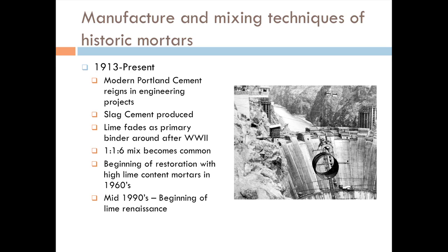And when you say lime, and you're talking about Portland mix, then you're also talking about something that was kilned at a higher temperature than the 900 or so that you were talking about, or are you talking about the regular hydraulic lime? I'm talking about just regular hydrated lime. When I'm referring to lime, only hydrated lime. That's what we buy today, and that's what's been, for simplicity, used for 3,000 years for the most part. ASTM C207. Yes. But it's not manufactured the same way because it's manufactured at a higher temperature. Am I right? To some degree, yes.